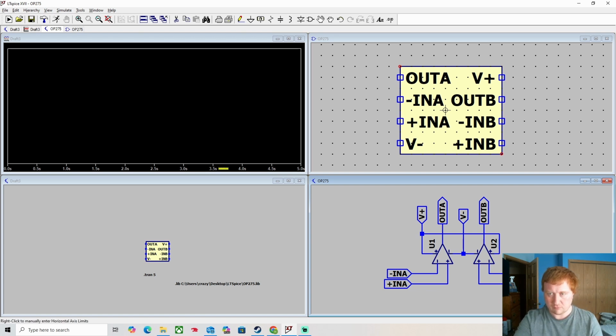So again, this is not the easiest method of doing a subcircuit, but it is one of two methods. The reason that you would have this setup is that a lib file technically takes up a little bit less space than if you were to do the subcircuit method without the netlist code.